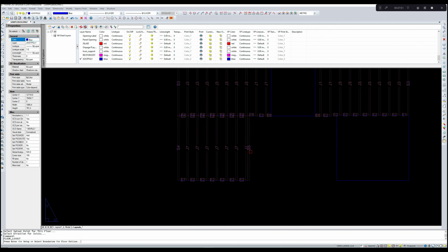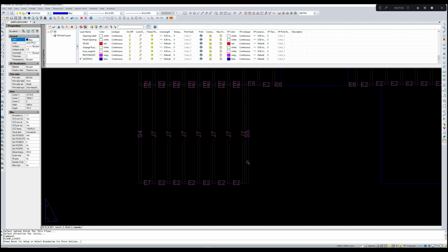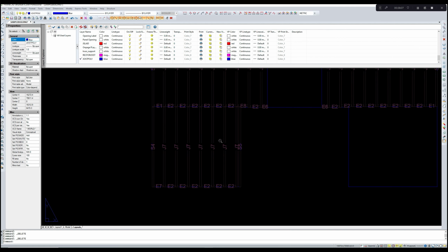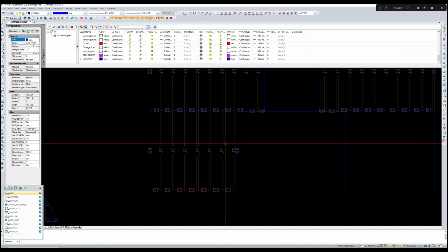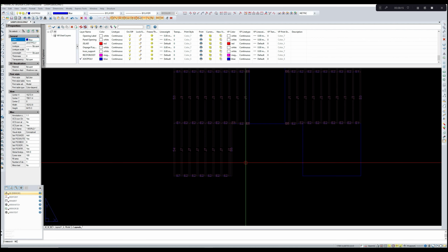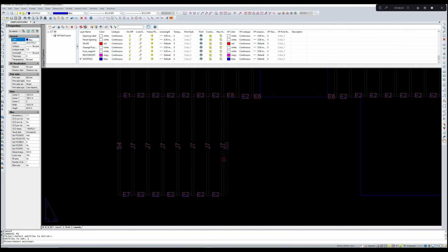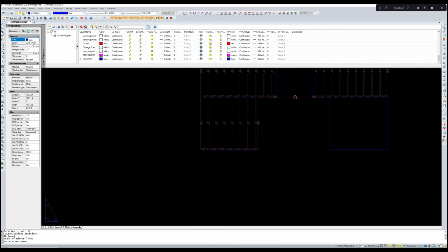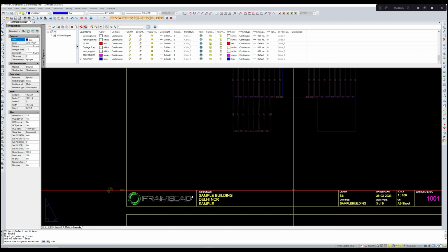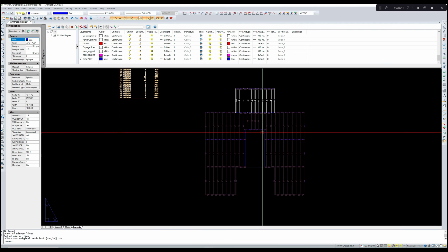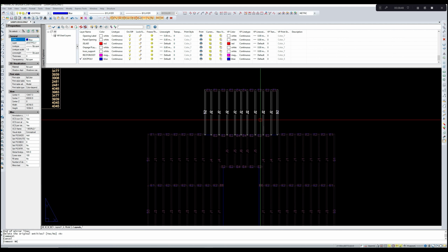So at this place, this joist will be placed over the wall, on top of the wall, so this joist would be required. So we do not need these blocks here. One set of blocks is already there as a separator between the joists. So let us mirror all these joists. Mirror is the command, MI, select the joist, then another joist, then the end blocks. Enter, go to the midpoint, drop a perpendicular to the border, enter. Now we have to change the property of this joist also. So let us match the properties of this joist with this.